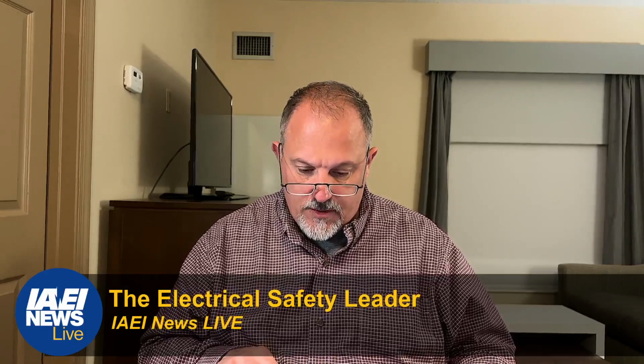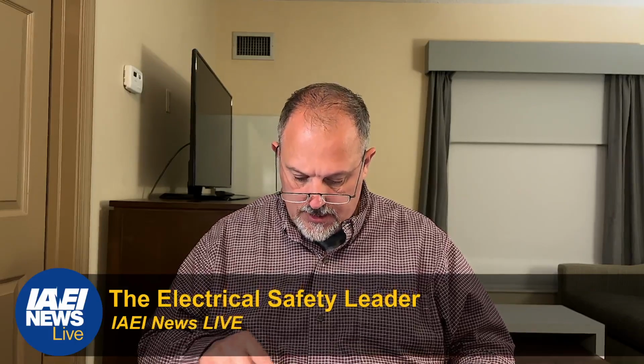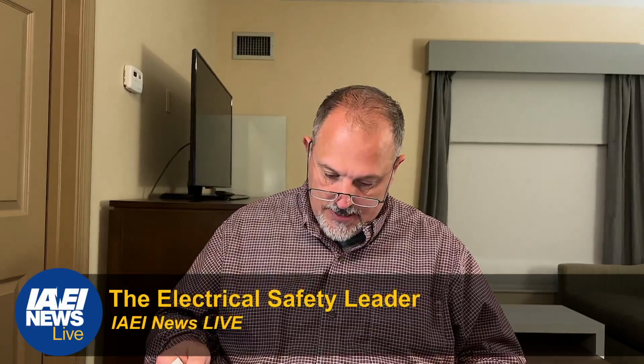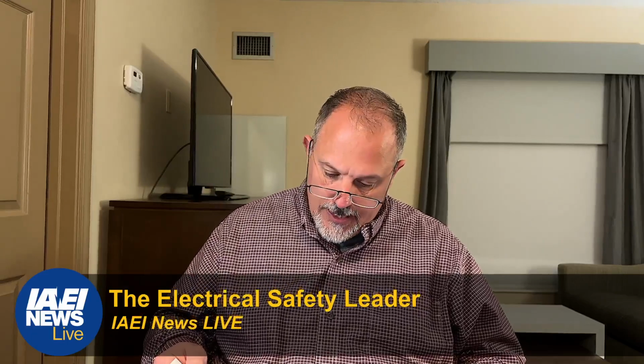We have indoor installations, 680.43. Indoor installations, receptacles, and then location, and then ground fault, etc. So it's there. We also have it in 680.44. Okay, 680.43 is your indoor installation. 680.44 is GFCI and special purpose protection.